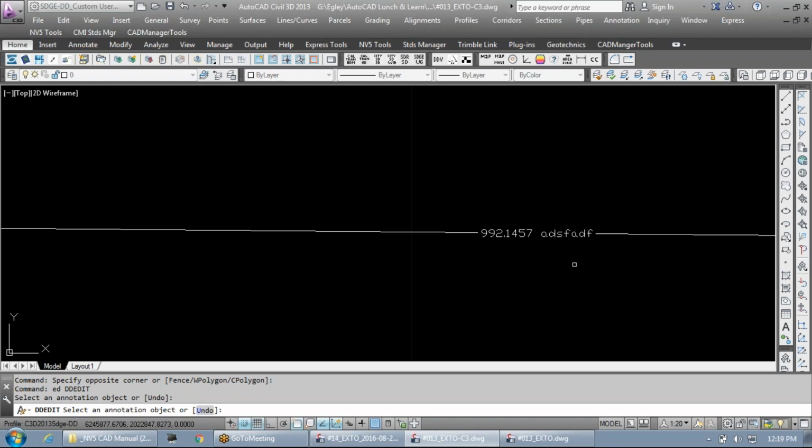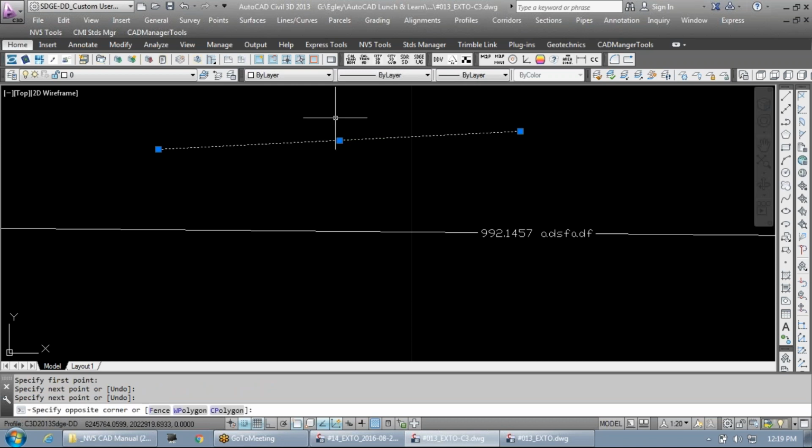The other thing dealing with file etiquette, the hard set of layer colors or objects, the hard set colors and line types. Make sure that you're not hard setting entities inside your drawing. Everything should be controlled by your layer manager. So the worst thing that you can see is somebody drawing a line like this on layer 0, right?